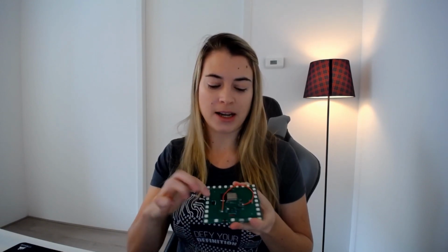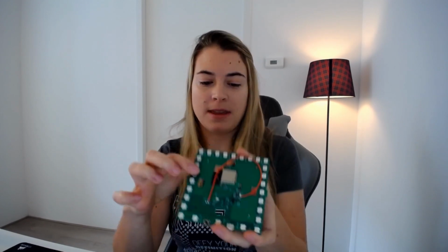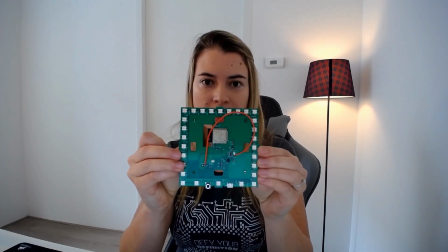So you'll see that there will be a specific layer, for instance, which will define the edge of the PCB. There'll be a separate layer which will define any drill holes that need to be done on the PCB. There'll be a separate layer for everything that needs to be on top, and there'll be a separate layer for everything that needs to be on the bottom. So this just separates everything and organizes it nicely so that the manufacturer can manufacture exactly what you want.